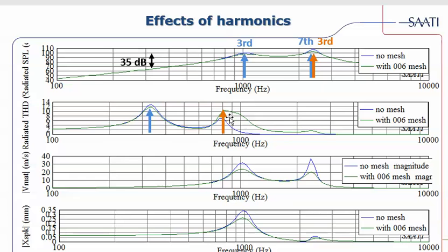Things are a little blurred out when you take the material distortion into account. We are having a strong effect due to this velocity with the material, but that's accentuated by the fact that we've got a peak in the response with its third order harmonic up at around 2.5 kilohertz. So I wanted to show this to you and point this out to you so you have a better understanding of what's going on with this THD generation.